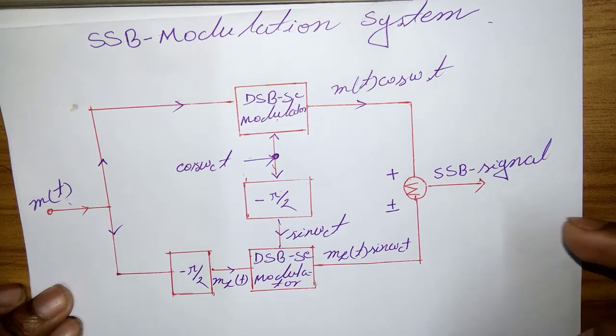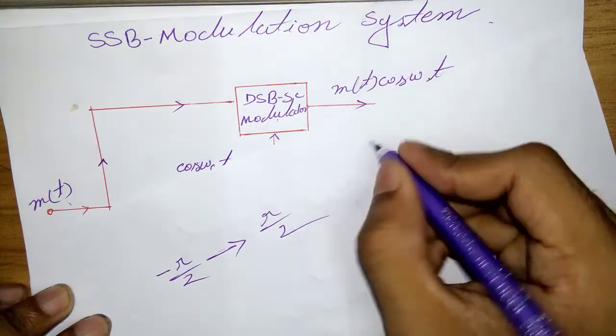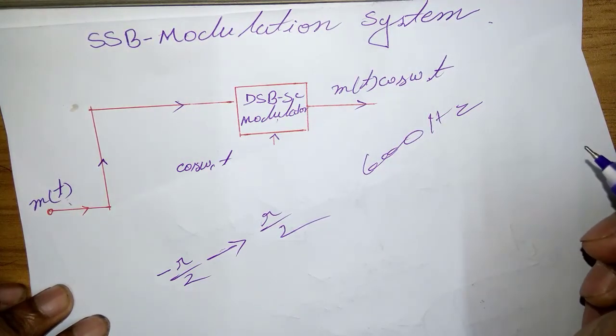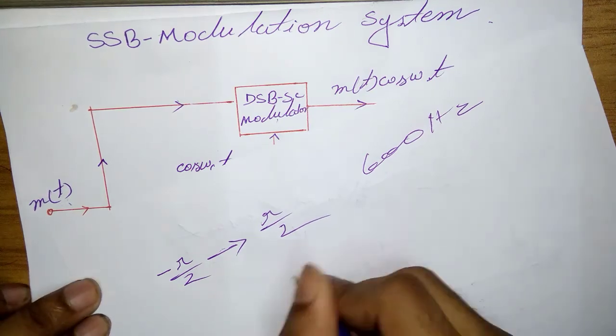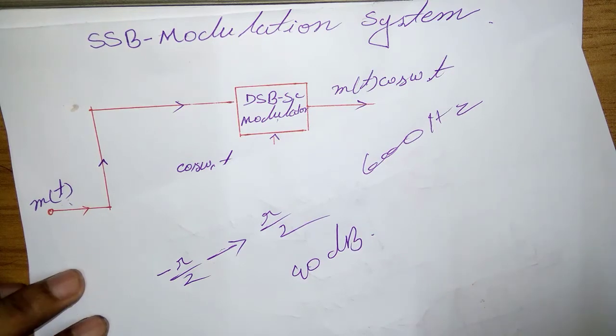In that case, for every higher carrier frequency FC, the ratio of the gap band, like 600 Hz to the carrier frequency, may be too small, and thus a transition of 40 dB, 40 decibels in amplitude over 60 Hz, may be difficult. In such a case, a third method is known as the Weaver method.